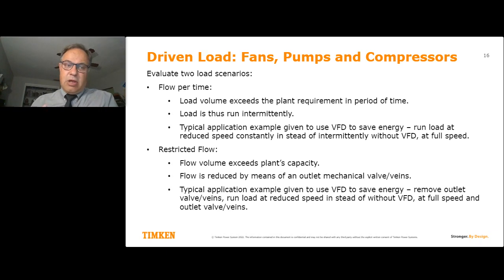Now, the question would then be, can I change it with a VFD that runs, instead of on and off intermittent duty, running at full or at a reduced speed, continuously maintaining the level of the plant? So that's one scenario I want to look at. The next scenario is very common, a restrictive flow.